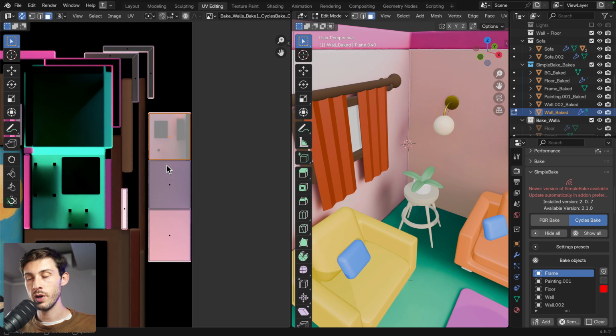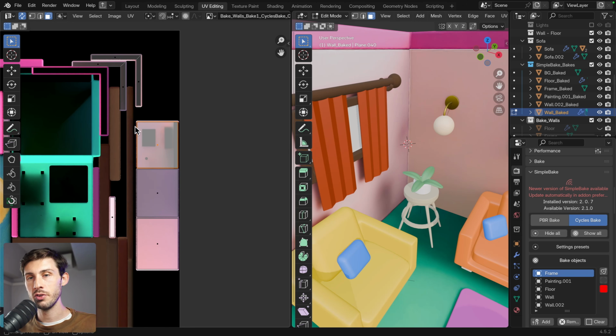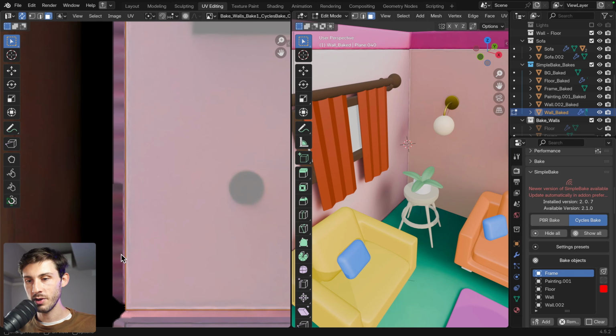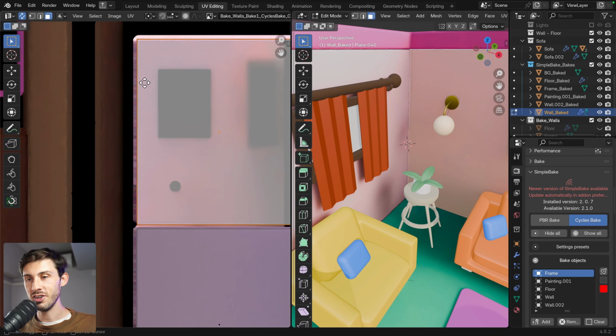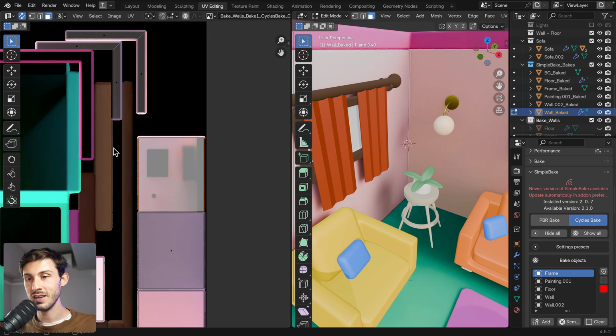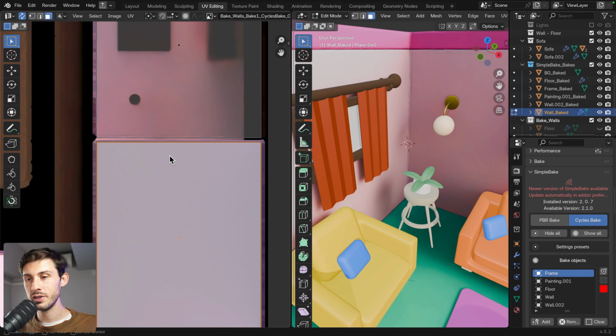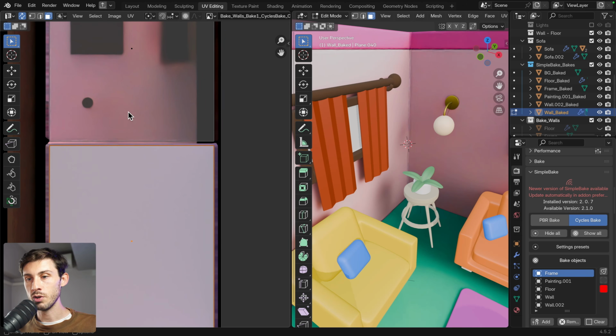And if we don't, when we bake, the precision is not pixel perfect. So we need to add some space, so when the baking goes over the edges, it's not impacting the other islands. Otherwise, it's adding some dirt and doing bad things to some zones.